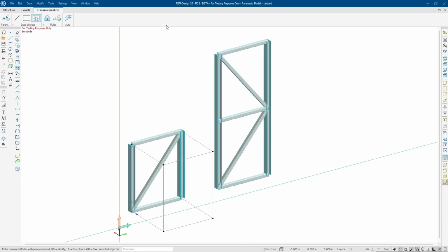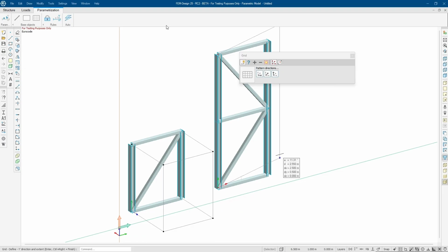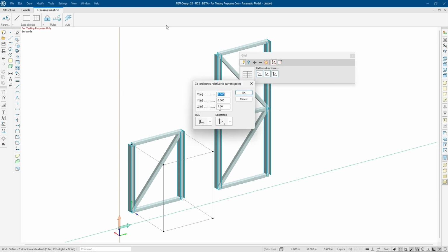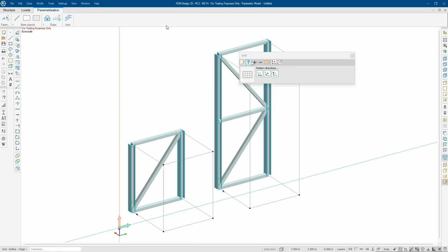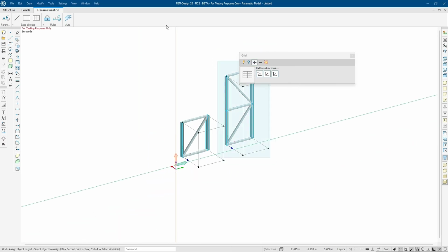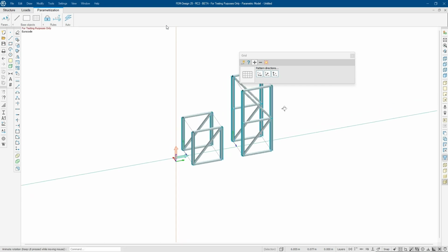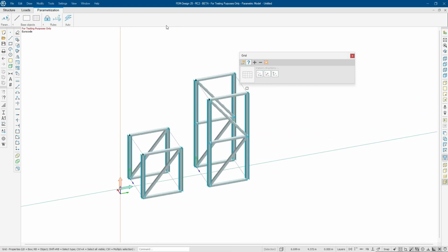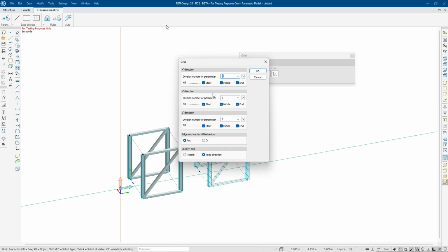And then I just wanted to show how this grid works in case the automation does not work. The grid is really fast. Also do it yourself. Just draw the grid with the grid tool like this. Okay, and then give it a size. And then we assign objects to the grid. So let's say that we want to assign these objects to this grid. And now it's done, and same here, these objects to this grid. So it's very easy to do also manually like before. But now the new automation will help you.